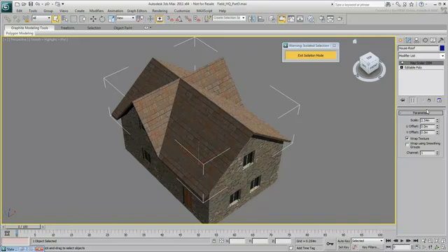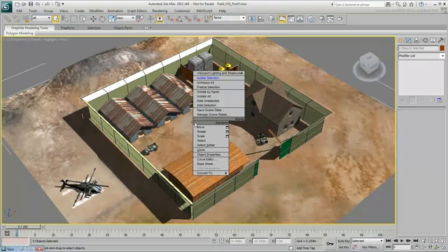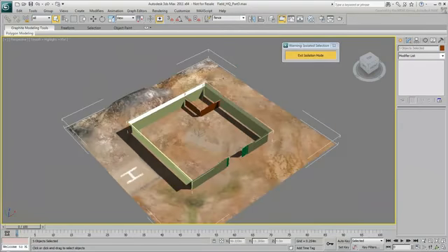into the model. Next, you can create a material for the chain link fence, which is an object you should be able to see through. Choose the fence selection set, then right-click in the viewport and choose Isolate Selection. Alt-click the ground to deselect it.